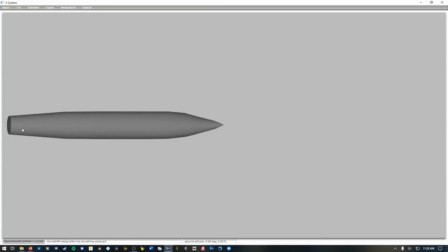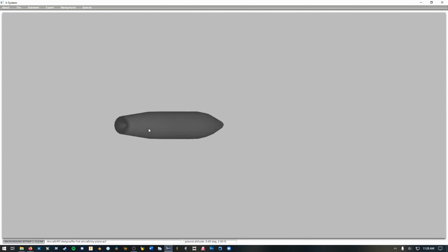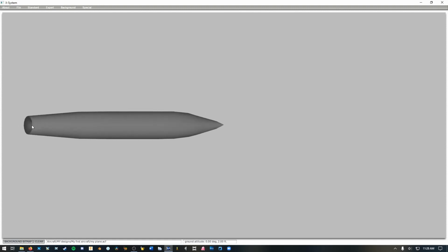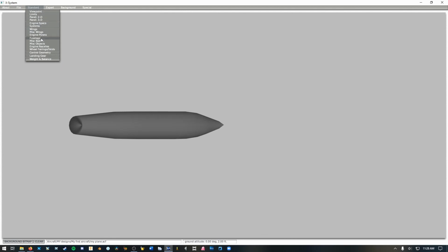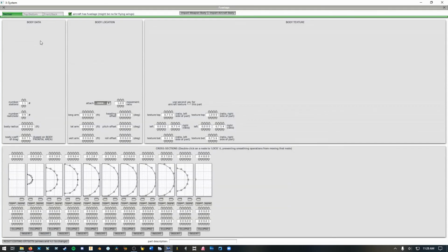Now what I just did there is I made my final point be a bit in compared to the furthest section away from the front of the aircraft. This is something you can do. You can offset these sections to basically wherever you want, and PlaneMaker won't try to stop you.